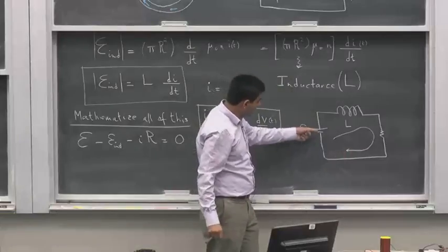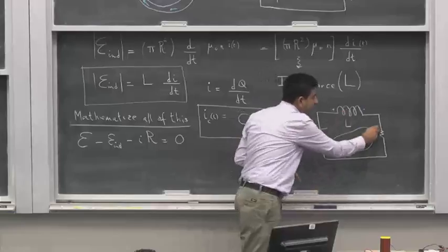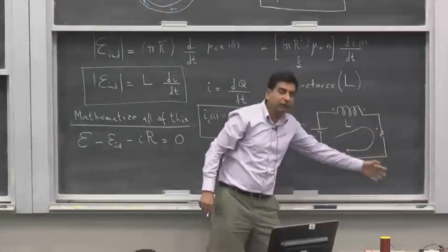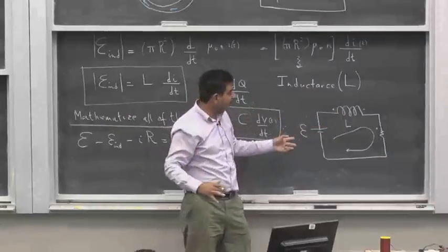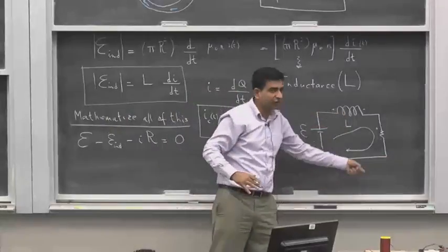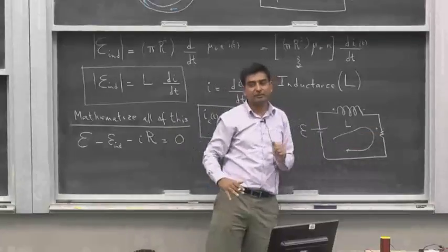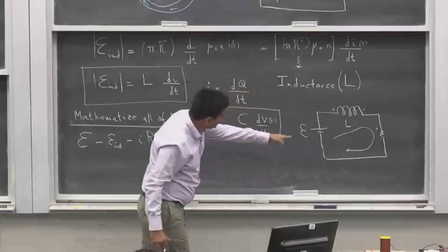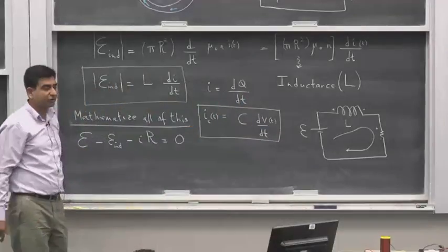It goes from minus to positive, then it goes from positive to negative, so it drops. Here it goes from positive to negative, so it drops. This current is actually flowing because of a charge gradient, which means that E dot dl has to be 0 across this path. And that's why Kirchhoff's voltage law is applicable. Alright? So if we look at this circuit, we would like to write a differential equation for this. This is what the differential equation is going to look like.